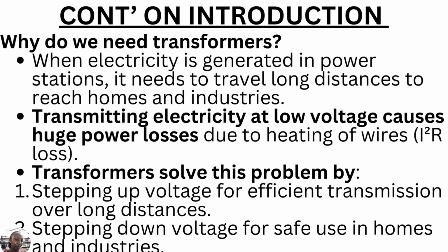So, why do we need transformers? When electricity is generated at power stations, it has to travel long distances before it reaches our homes and industries. If electricity is transmitted at low voltage, a lot of power is lost as heat in the transmission lines.